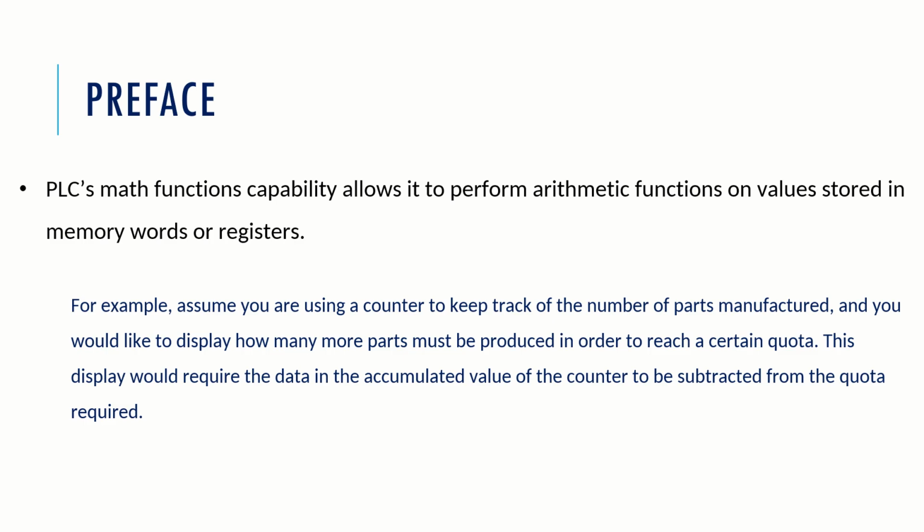Now you see that these math functions in the PLC allow it to perform arithmetic on values. Whenever we are talking of arithmetic functions, those functions have to be performed on some values. So such values have to be stored in memory words or registers. This is one important aspect that you should remember: whatever the values are, they should be stored somewhere, because unless they are stored, the PLC will not be able to perform the arithmetic functions on such values.